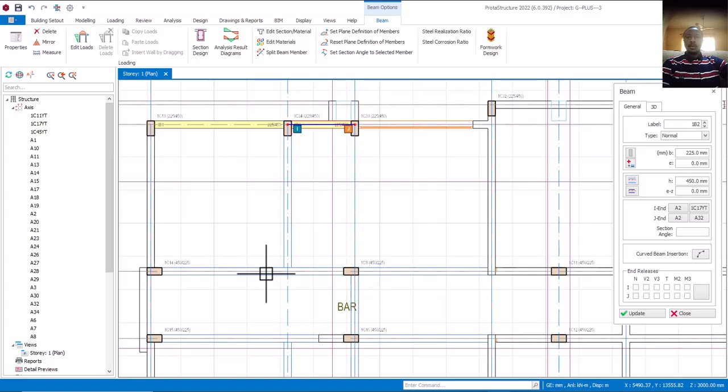So now this particular place, I'm trying to insert it. Can you see what it's giving me? So I'll come here, come to general. Under general, I'll come to this place called pick point. Then I'll pick this point, come down and pick this point, then go up and pick this point. Can you see now we have formed our slab? That's what I'm going to do for those places that are giving me such issue. Just let me show you.